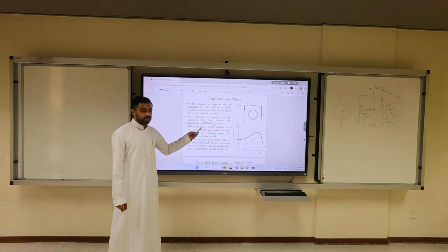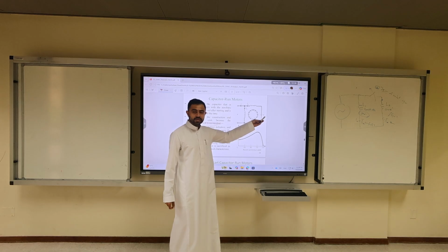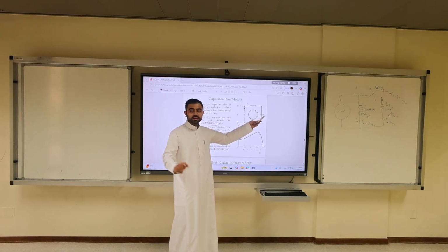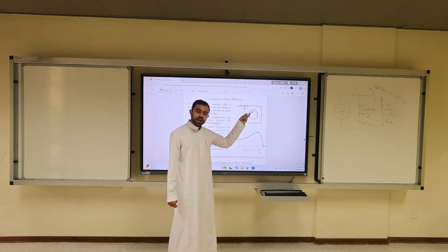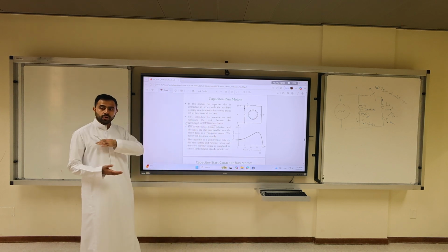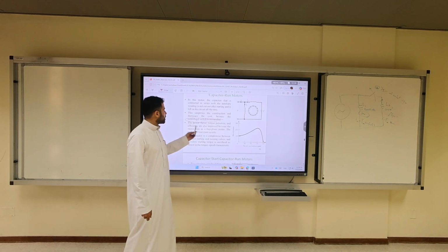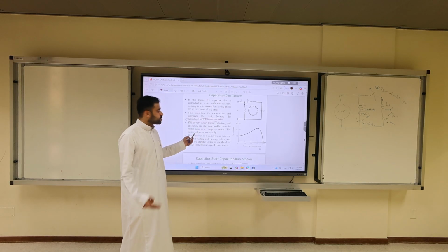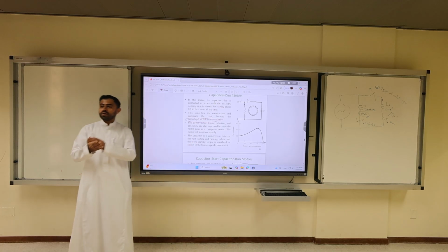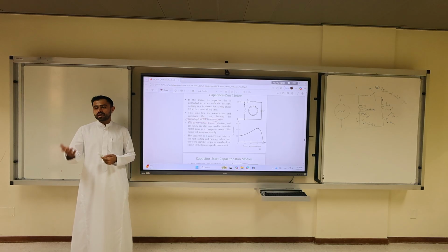It may reduce the cost, but as I told you, the issue is, if this capacitor is damaged, you're done. Your machine is not reliable. So you tie your reliability to this capacitor. And this capacitor, if you keep it on all the time, it causes a problem. The power factor, torque, efficiency are also improved because now you have two phases. So the more phases is more efficient. A 5-phase machine for space industry is more efficient. For military applications, they use 5-phase.